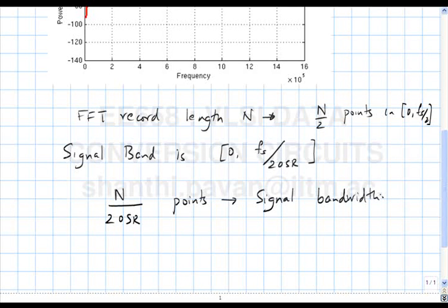Okay, now we have a variety of choices for the spectral window. One is, as we have seen, the Hanning window. The other one we saw in one of your assignments was the Blackman-Harris. The advantage of the Blackman-Harris is that while the main lobe is wider, about 9 bins wide, the side lobe attenuation is much larger than the Hanning window itself. So the question is, if you have a wider main lobe and smaller side lobes, that seems like a smart thing to do, right? Any comments on why one might want to use a Hanning window over a Blackman-Harris window? Yes. So what? All the bins within the... Pardon?